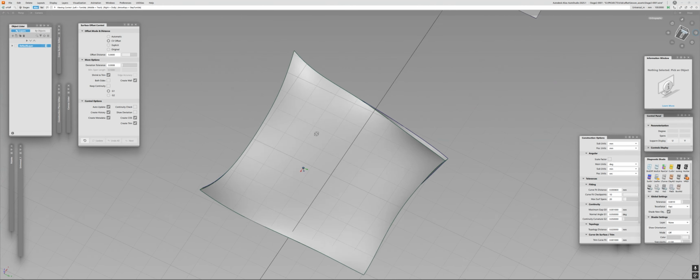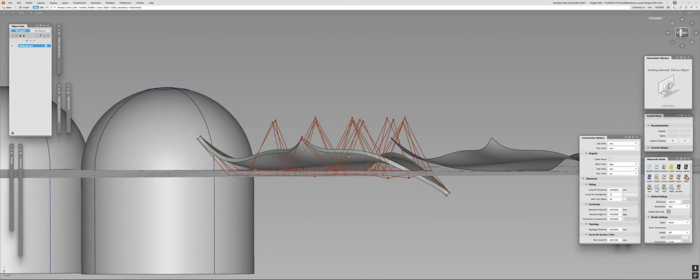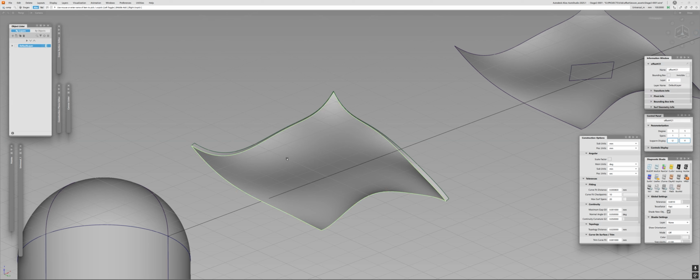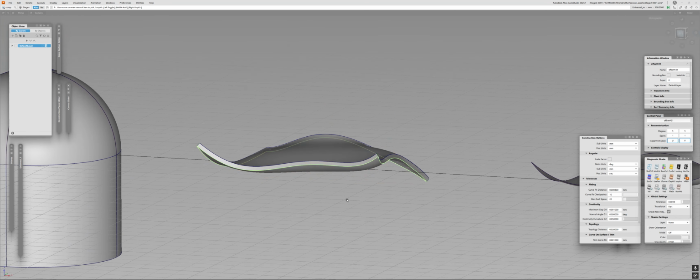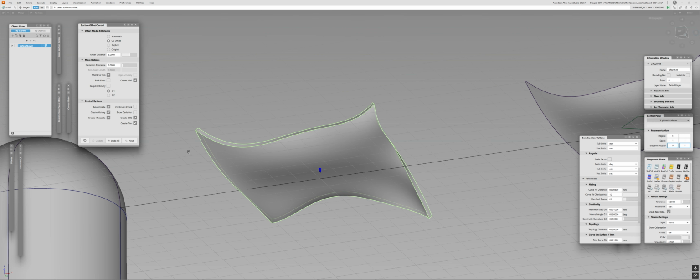Second, it gives you a surface on which you can still sculpt further, and the CVs are offset from one to another. So it can be a pretty good solution when you need to cut something, add an additional transition, maybe something else. Not just Boolean operations on the solids, but in terms of surfacing. So here, as you're going to see, the CV offset works great.